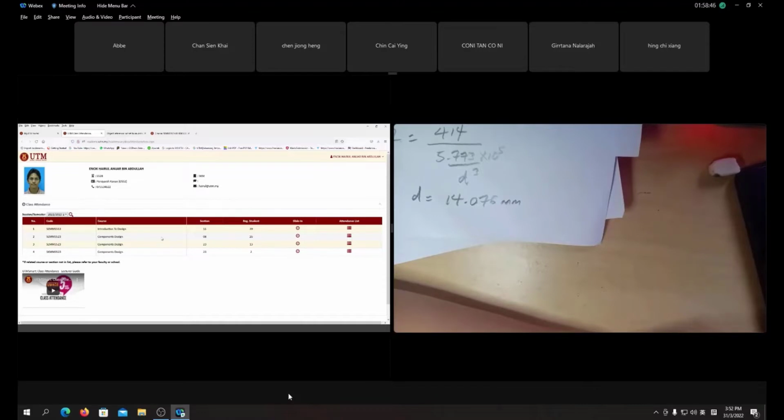Nanti later on you punya question 2 on your test 1 will be fatigue. Fatigue tu little bit you have to know lah. Little bit fatigue analysis, you punya strength is no longer SY, endurance limit SN. Just now safety factor is SY over your sigma E, but fatigue, you not use SY, you use SN. SN is lower than SY because loading you variable, loading you fluctuating.